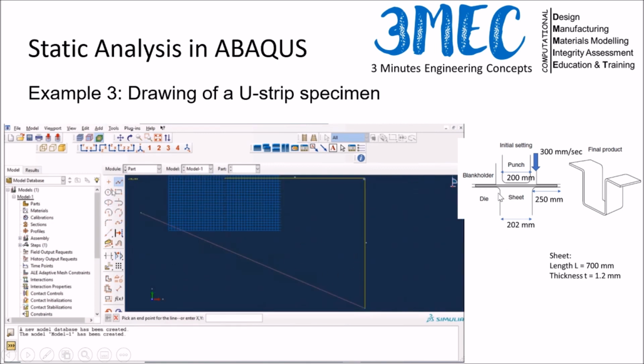And it looks something like this, and then I will select this fillet command from here and create a fillet, and I am assuming the fillet to be most probably 50 millimeters. Yes, so I'm using a fillet radius of 50. Again, this comes from the part geometry and also the springback.